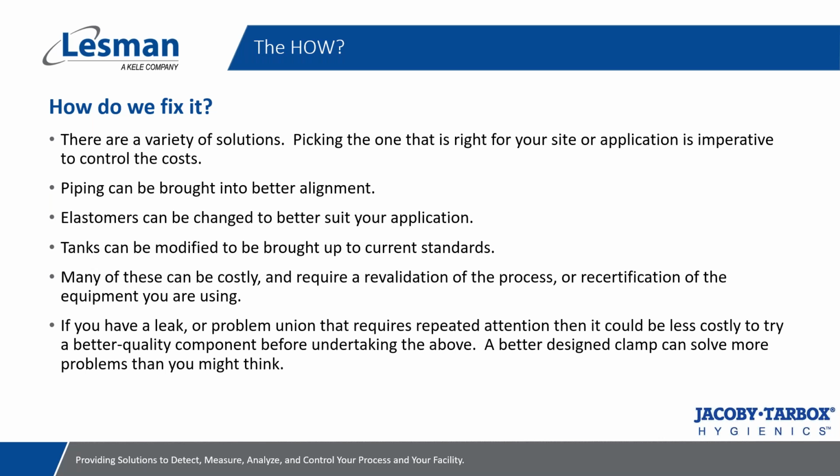So we'll validate the process using all of those, as opposed to using just EPDM only to find out that EPDM doesn't work in this particular application because of our temperature variations or the caustics that are involved with our cleaning and sanitation programs. So if you have a leak or a problem union that requires some type of repeated attention, meaning for some reason, I've got to continuously be revisiting this connection.